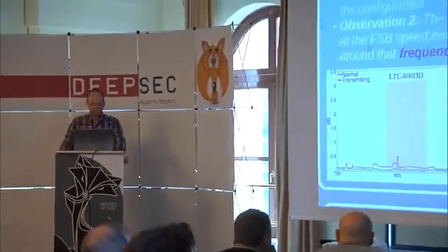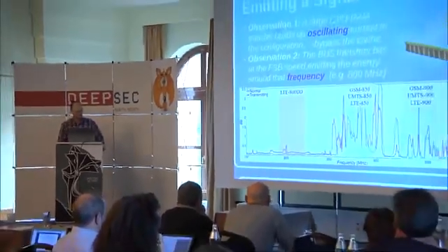So what you see at the bottom is a plot. The blue line shows the regular noise floor, which could possibly be other cellular phones communicating or other computers in the room causing noise. The red line shows the added energy received across the spectrum when we cause this large transfer between the CPU and the memory. It's important to point out that it's not just any transfer. You have to bypass the cache in order to get this large buildup to occur, and then the emission will happen. So we affect not just GSM, as the title GSMEM may imply, though we tested specifically GSM. But as we can see here, all these different bands of all the different technologies receive the signal quite well.